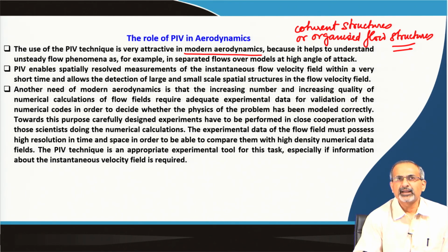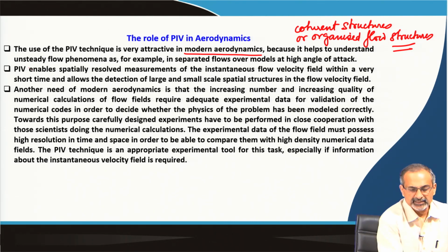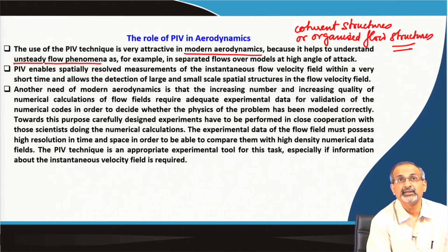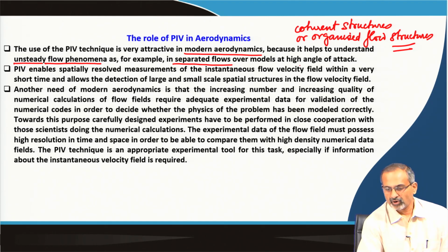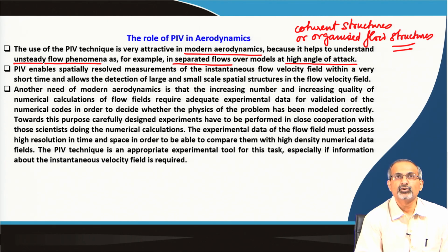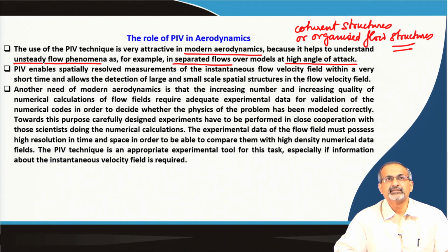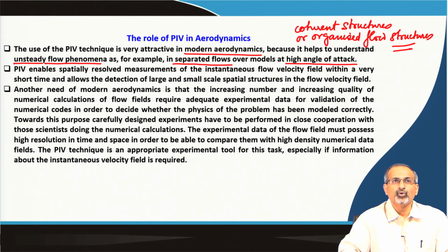Therefore, you can apply it to different kinds of flow situations, of course to steady flow situations, but more interestingly to highly unsteady flow phenomena, where you can have separated flows, time dependent flows on different configurations at high angles of attack, etc. Therefore, particle image velocimetry is a very important tool in studying a whole lot of complex flow phenomena which occur under unsteady situations.